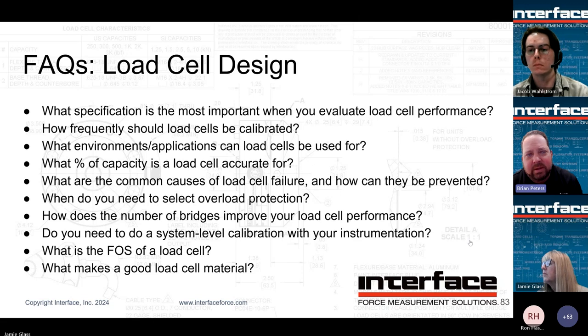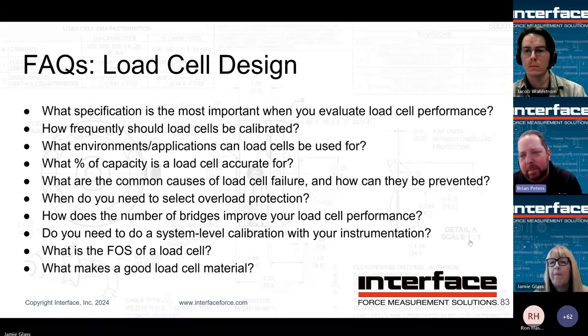So we would recommend that the live end is closest to what you want to test. Because if you have that dead end with additional base and the cable, you could have some minor parasitic or inertial aspects impacting what your DUT is seeing versus what the sensor is reporting.